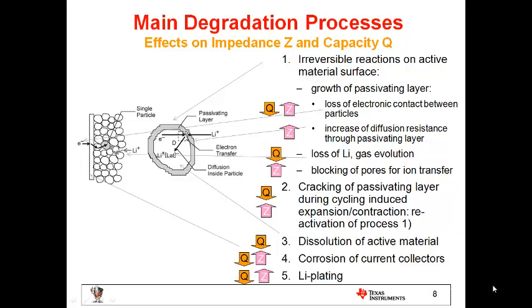First, we need to have a quick look at the insides of the battery to understand the structure of its electrodes. So pretty much for all lithium-ion batteries, both anode and cathode would be a current collector and particles of active material that are kind of piled up and compressed. You can think about it kind of like asphalt. So it has some solid particles which are held together by the binder, and there's also some conductive additive.